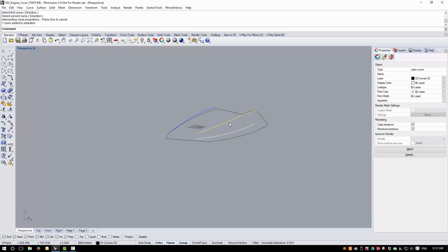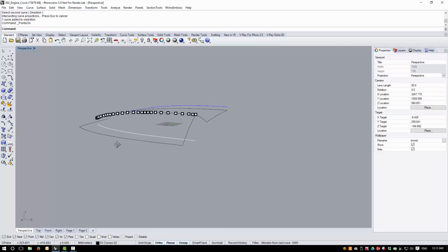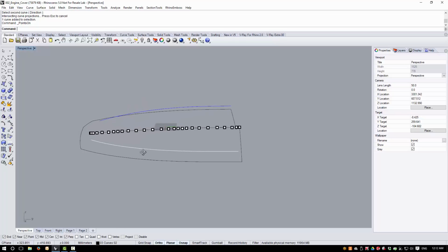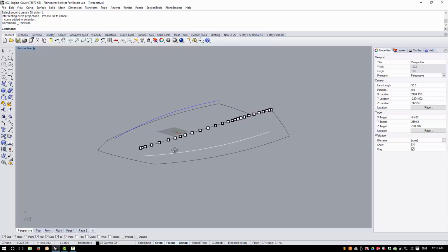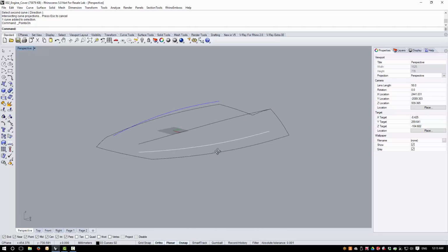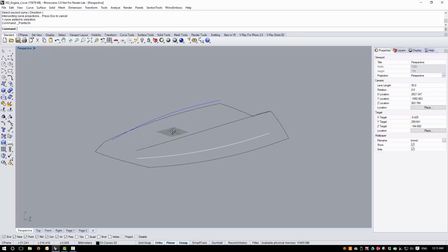Now this command works by essentially projecting the two curves until they hit each other in 3D space, and as a result the curve that we generate here is much more complex than the original curves, and it isn't something that we can use directly in this case, but we can use it as a guide and to check that the position of our clean curve is correct.